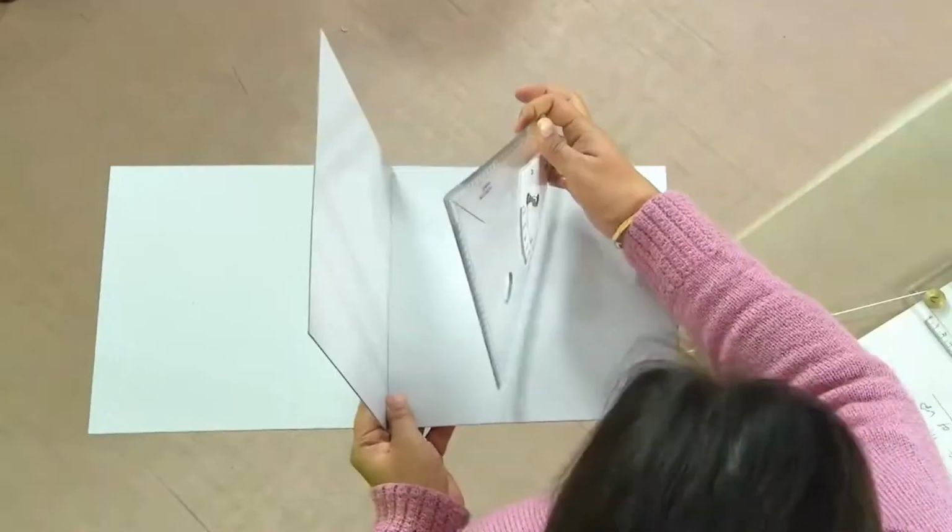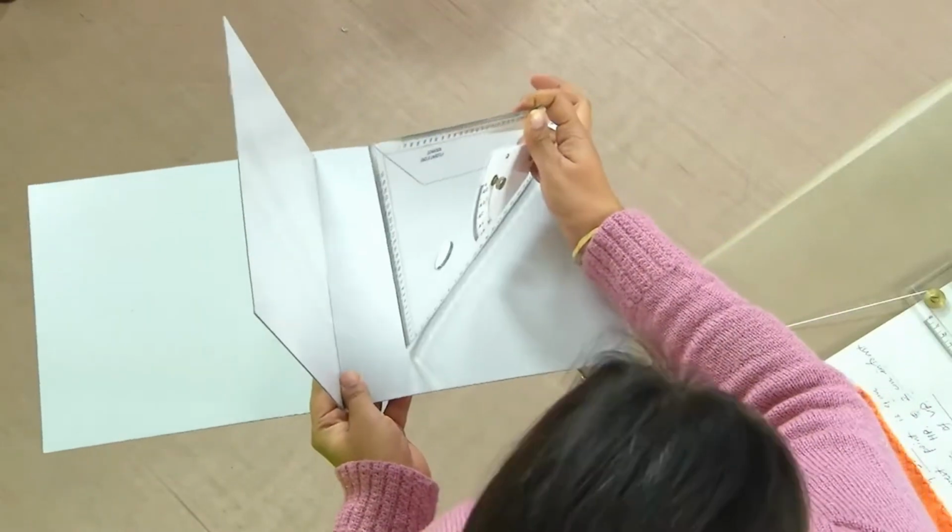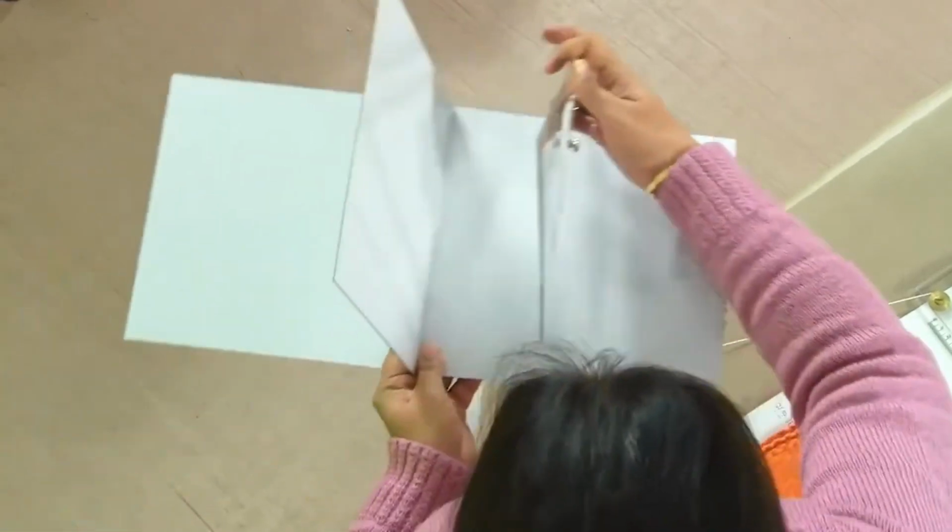What if the plane in question is perpendicular to HP and parallel to VP, and then it makes an angle with VP? This is how the change happens. Right now it is parallel to VP, perpendicular to HP, and when we incline it like this, it becomes inclined to VP and we see a changed shape in VP, which is its vertical trace.